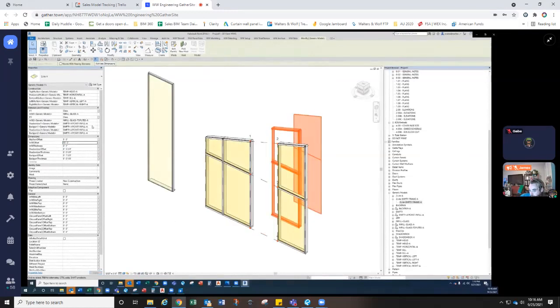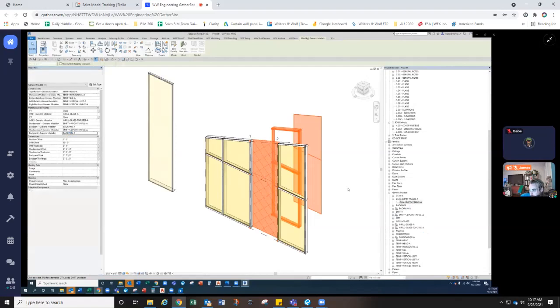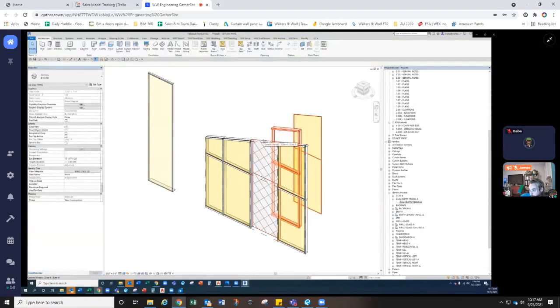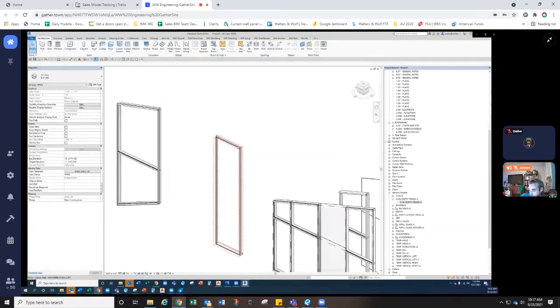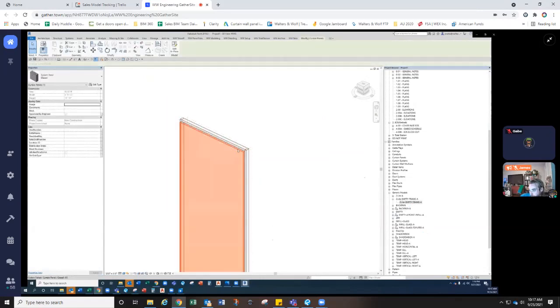I'm just trying to demonstrate how these are being made to replicate G units, so you don't have to learn a whole new process for how these function. You just really have to learn the way of loading them in, selecting them out of your generic models section, and then applying an empty frame and switching that empty frame out for the frame with all the mullions.